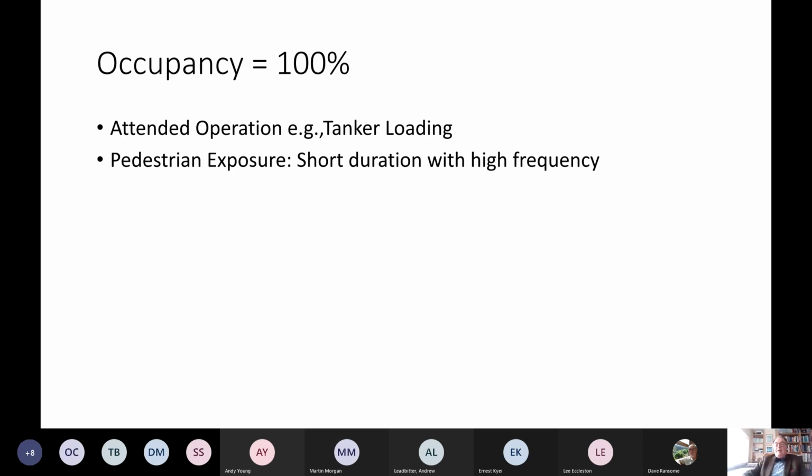If you consider that the hazard, let's say the hazard is present for 1 hour, because the hazard persists. It's not a transient thing. It sits there for 1 hour potentially. If somebody passes through that area every half an hour, although they're only exposed for the 10 seconds, you're guaranteed that when that hazard arises, because it persists for an hour, somebody will be exposed. It becomes a certainty. So in such examples, we cannot claim occupancy as a conditional modifier. It becomes, in fact, a certainty, and it becomes 100% again.